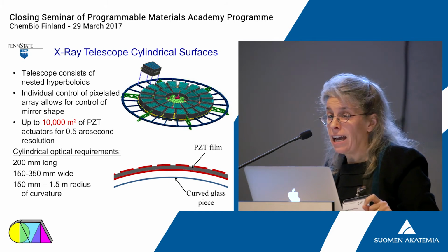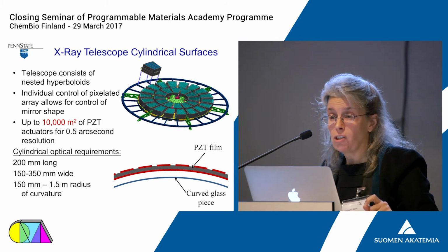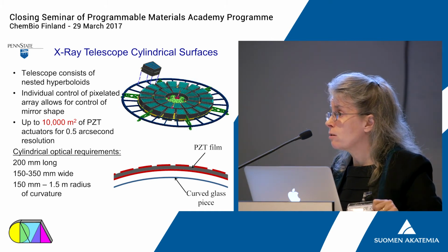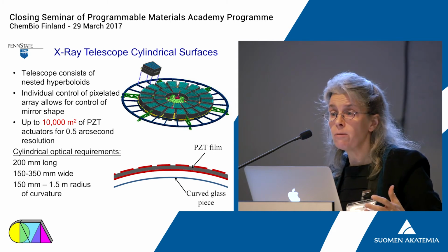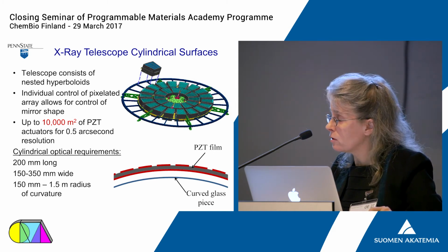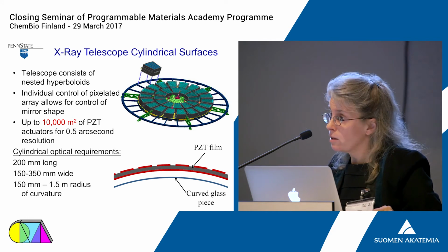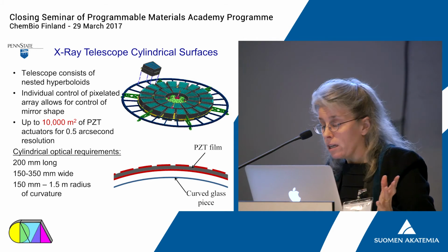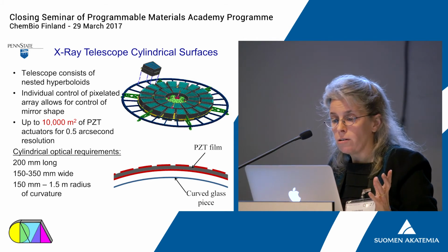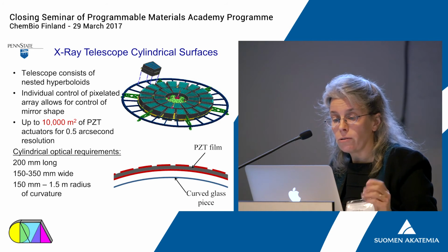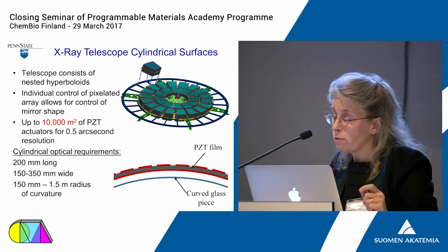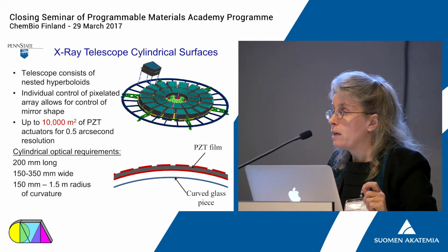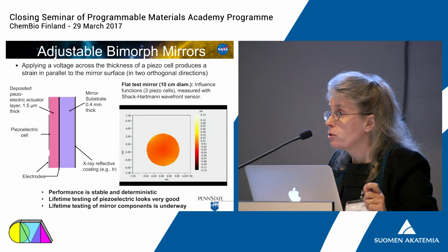And it was that much glass literally because they needed it to be so stiff that it would not deform when you launched it into space or on gravity release. The problem is with only 4 reflecting surfaces, you are limited in terms of the brightness of the objects that you can detect. And so the Smithsonian Astrophysical Observatory said, if we're going to launch, it's been variously called SMART-X or the X-ray Surveyor or the Lynx telescope, we really want more reflective surfaces, which means the glass has to be thin. And now we need to be able to correct its geometry if it's incorrect.